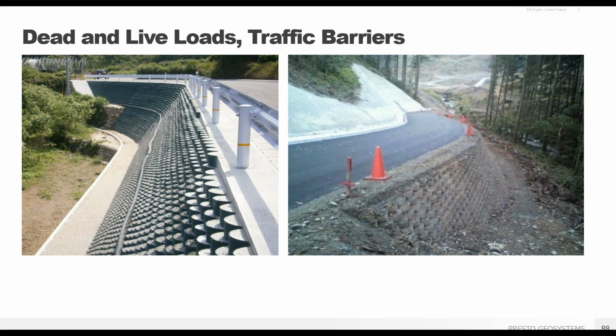When possible, the load should be placed away from the edge of the wall or the fascia. If not, the design will need to be robust enough to support and withstand that live and dead loading. Having traffic barriers at the top of the wall will help keep the loads away from the front face of the wall system, which will help with the design.